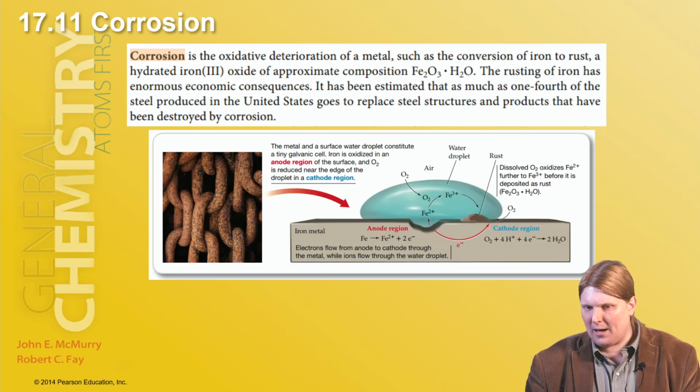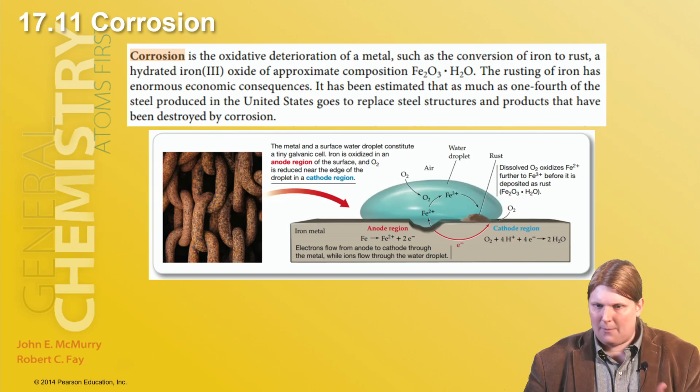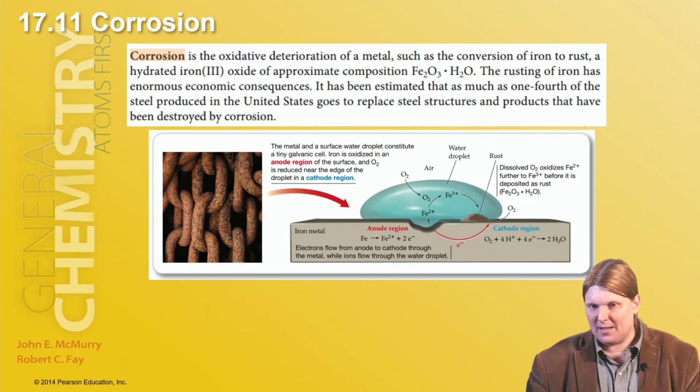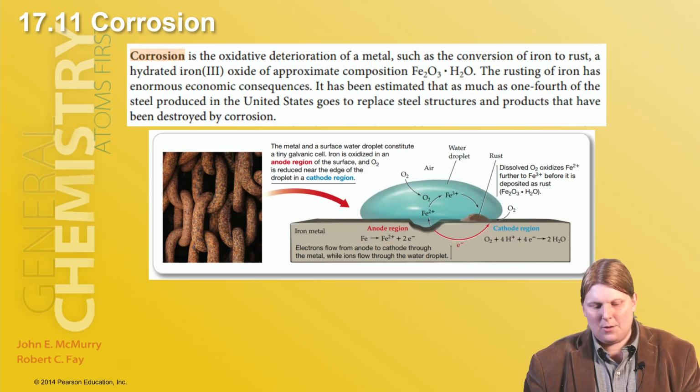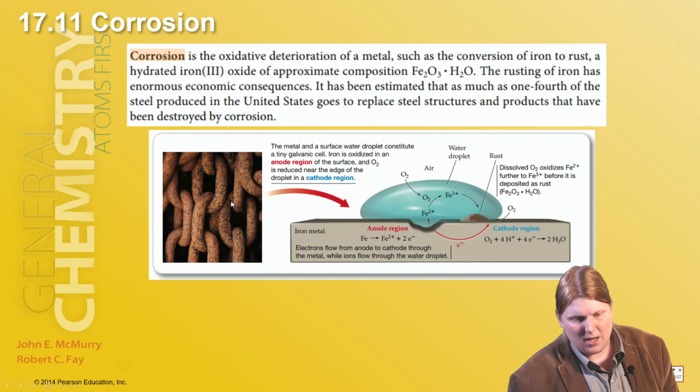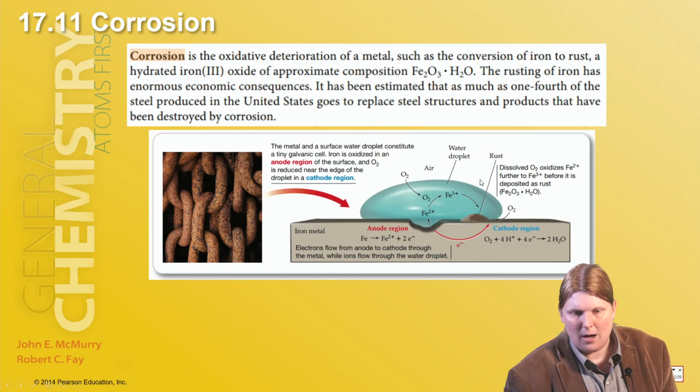Metals that do have the oxide adhere to the surface include things like aluminum, magnesium to some extent. These metals are very active metals, as we saw on the standard reduction potential chart, but they coat themselves in a protective oxide layer that prevents further corrosion, so they don't rust like this. The oxide layer for iron is just simply not protective.